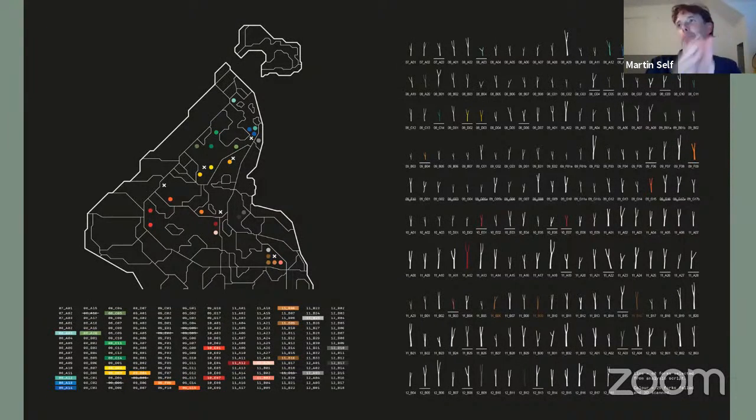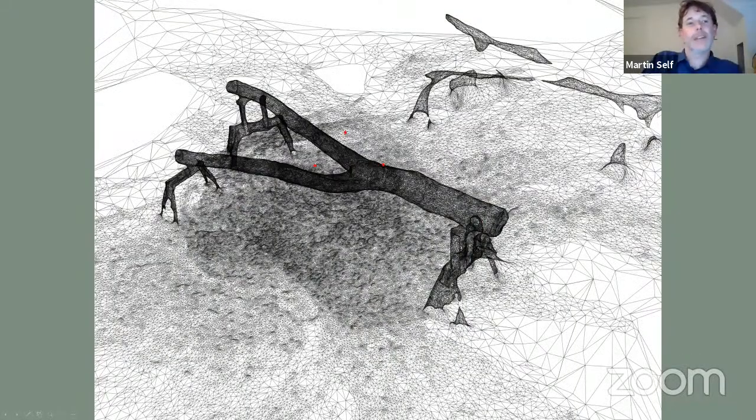So we understood what the typical branch angle was, the 20 degrees or so that you would typically see. Iteratively working with the engineer, that informed the truss geometry they were going to be made into. So there's quite a lot of backwards and forwards in the process. The structure was designed from this data, in its principles. Then out of these, 25 were selected to be used for the 20 forks that went into the truss. They went through that process with a much more detailed, full 3D scanning.